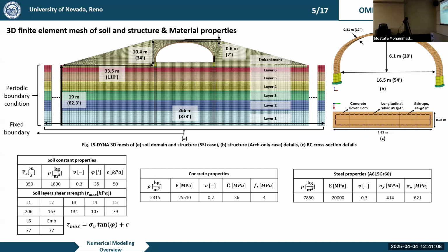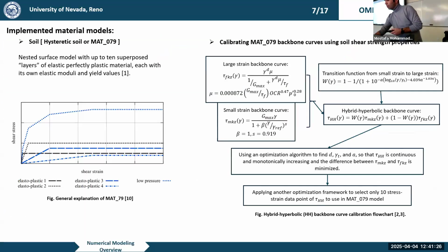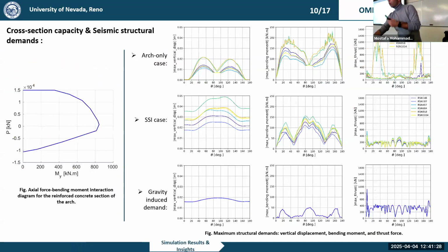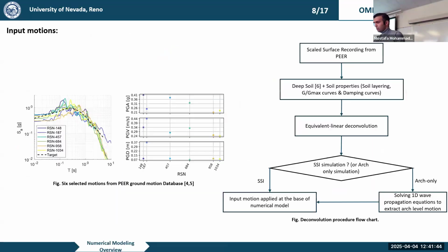Because, as I told you, I took these details and specifications from a previously constructed one from the Pennsylvania Department of Transportation. They were using that. And I was just in the very early stages of modeling this. And as you saw, our demand does not make our structure nonlinear. One of the main reasons is the dense spacing of the reinforcement. So if you change it, probably it would not make very much difference from what we have right now. But this is the reason that I used that grade of steel.